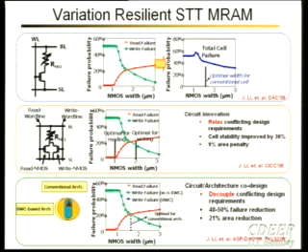What we looked at is, remember that in the last lecture I was talking about how the read and the write have to be separate, or ideally, if you can separate them, that turns out to be good. And that's exactly what is done in the second one, where I can separate everything using 2 separate transistors. Now, if I use 2 separate transistors, I pay in terms of area, right? And that's a problem. The second thing, of course, is any architectural solution, like making my read good and write bad, or giving write a little more time. And then it turns out you can do various kinds of things, like the last time I talked about.